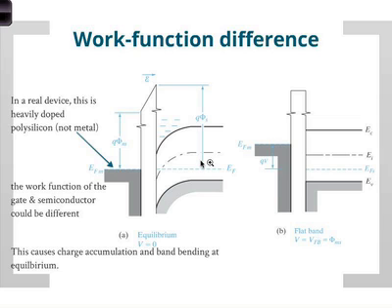Which means that under equilibrium, I have to have some band bending. So this is the diagram under equilibrium. Before, under equilibrium, everything was flat because the Fermi level was flat and these two numbers were equal. But now we know for a real situation, they're not the same, which means that the Fermi level still has to be flat, there's no current flowing. So this whole thing has to bend down. So this is at equilibrium before you apply any voltage. In other words, there is a built-in voltage, a built-in field, almost like a p-n junction.